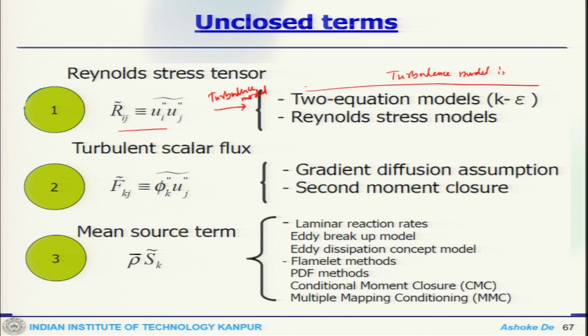model in the RANS framework. We are not talking about anything on LES because the equation system would look slightly different. So, any RANS based model, like two equation models, k epsilon, k omega, or RSM, would close this, and it will only give rise to the questions and all these things that we have already seen as a part of our discussion on turbulence modeling.